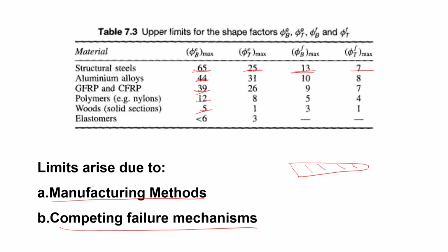Now, corresponding to this case, if bending comes into the picture, and if we have three such materials possible, the wood, CFRP let us say, and the aluminum, interestingly you would see that though material property index wise wood is better, that is what we have seen in the last class, if we consider the shape factor, wood is no good.